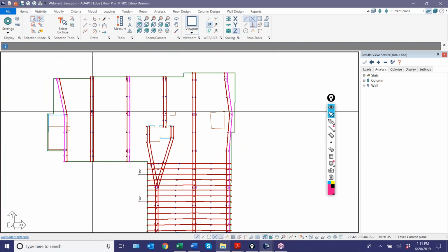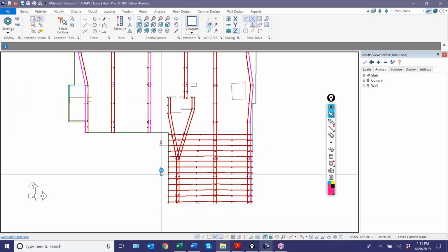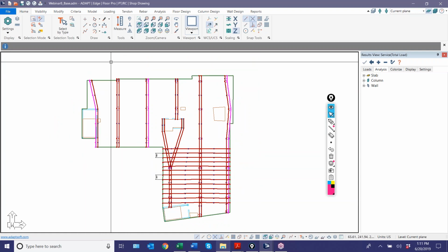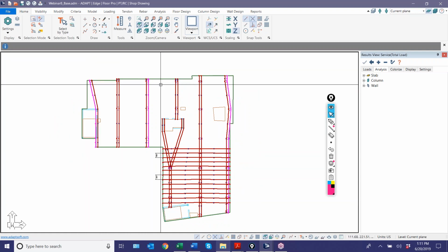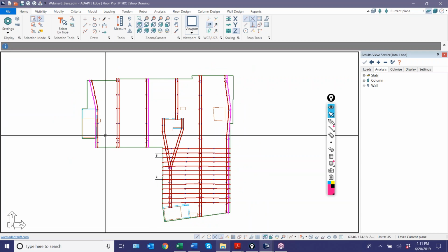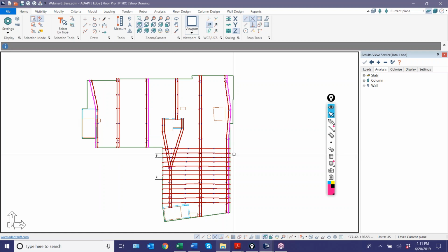Because if I map 10 different ranges, technically, depending on the loading on the slab, you could end up with 10 different spacings. So a lot of times it's actually easier to just model a cable and then use uniform spacing throughout and just adjust the number of strands as needed when you go through the iterative design process.